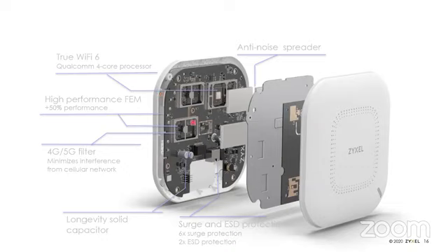The other thing you'll see when you look at our board is we've got a lot more shielding around the chips on the PCBA, both to protect from interference from LTE and 5G radios that are operating on nearby bands, but also to help with EMI. So that gives us a little bit of a performance boost. Then on top of that, we've got another big chunk of metal. It kind of acts as a heat sink. It also helps distribute noise, and we mount our antennas to that. Most of our competitors, even our more expensive competitors, mount their antennas directly to the PCBA, where they're much more likely to pick up some EMF, which can result in worse signal to noise ratio.